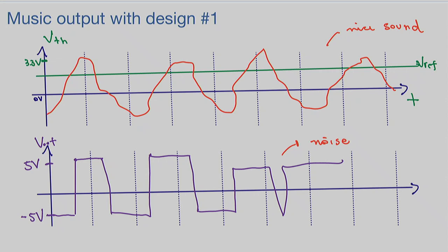Yes, go ahead. So I had a couple of questions. One was, is distortion when you clip the signal once it hits a certain point, or once it passes a threshold, it goes from -5 to 5? Yeah, so in this case, we were passing the threshold, and in our design, we were just throwing the signal to VDD and VSS based on that reference that we had. So that's why the signal was completely distorted. It was not what we started with, right? That means that our amplification was too much.